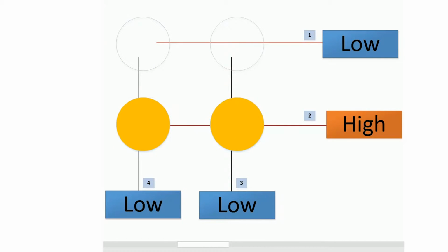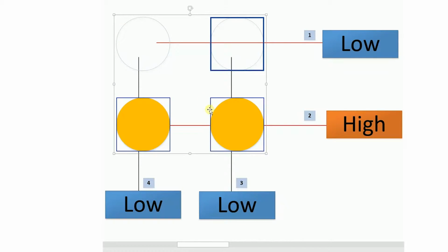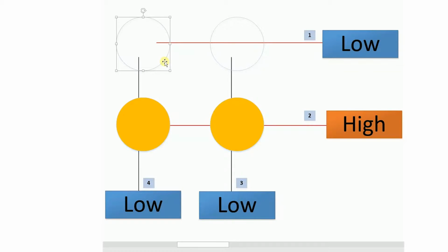We would have to turn this row to high and this column to low, which it already is, to turn on this LED. Say we want to turn on these 3 LEDs and leave the top left one off. Well, in order to turn on this LED, the top right one, the row would have to be high and the column would have to be low, which it is.